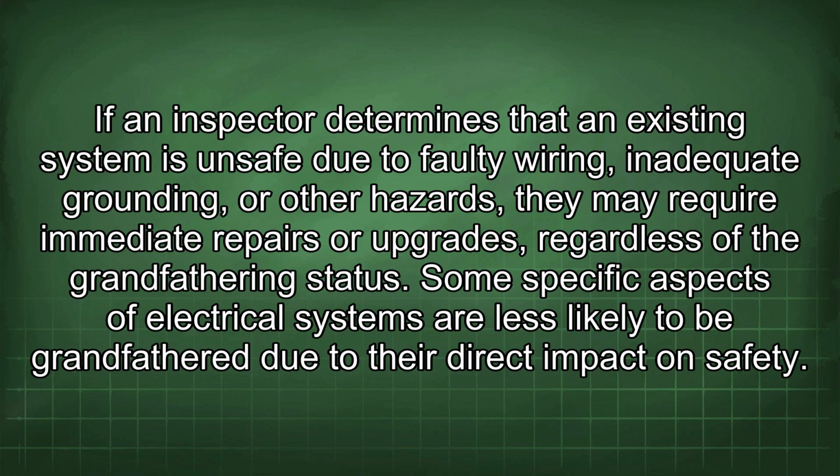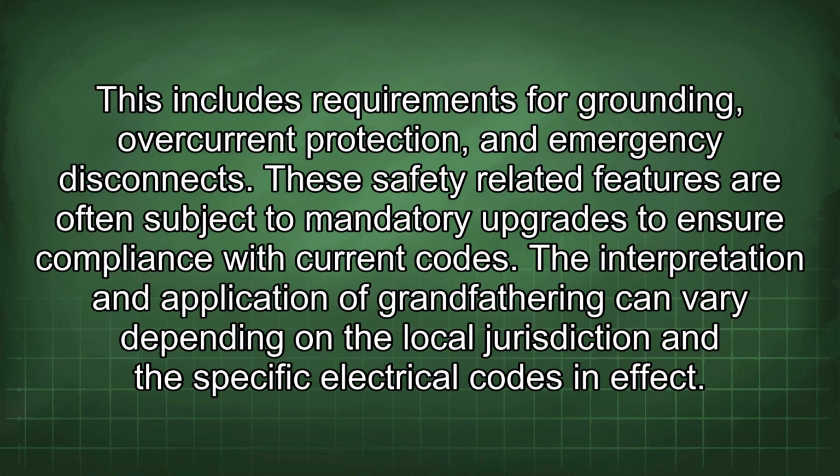Some specific aspects of electrical systems are less likely to be grandfathered due to their direct impact on safety. This includes requirements for grounding, overcurrent protection, and emergency disconnects. These safety-related features are often subject to mandatory upgrades to ensure compliance with current codes.